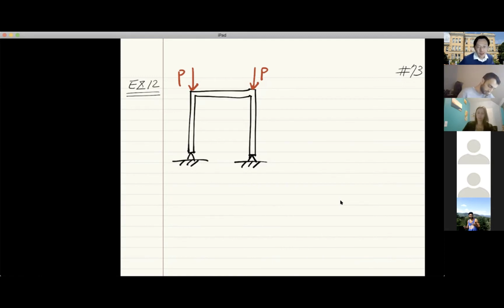Now, in the buckling of this kind of structure, there are possible scenarios because the structure has more redundancies. That means it actually has more degrees of freedom. That also indicates that the failure of the buckling mode includes more possible kinematically admissible deformation profiles.